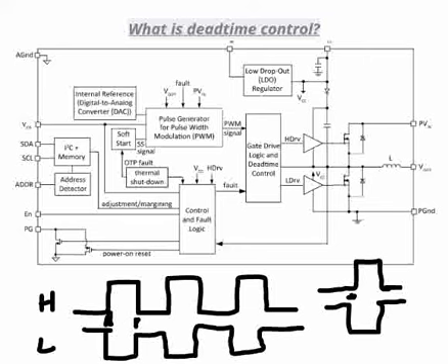But if you take the regulator chip that is available, like the example one which we are seeing here, the dead time control is ensured. So when you are selecting a regulator, see that this feature is available, and most of the regulators do have this feature. And as we mentioned, when there is external control, it has to be taken care of by the user. Thank you.